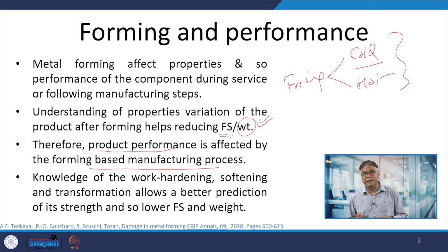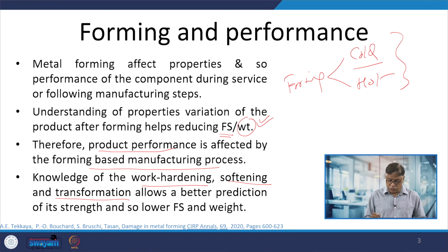So, we will be talking in detail about these aspects. Understanding and knowledge of work hardening or even softening under high temperature, or the phase transformation if it is taking place under either low temperature forming conditions, meaning cold forming, or under hot forming conditions, will help in better prediction of the strength, and so lower the factor of safety and the weight of the product.